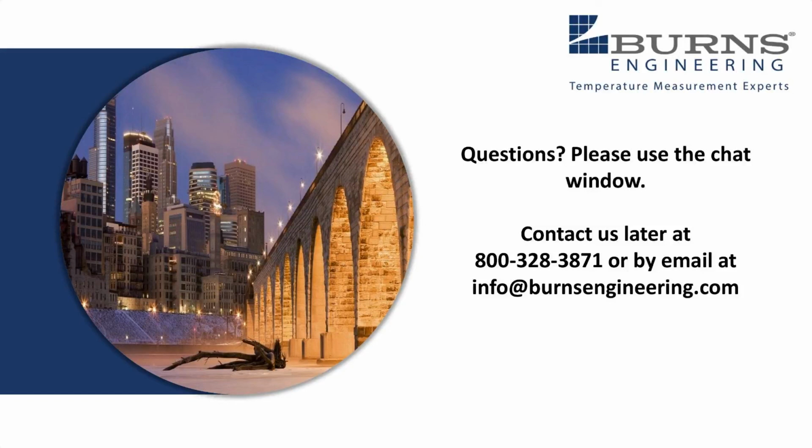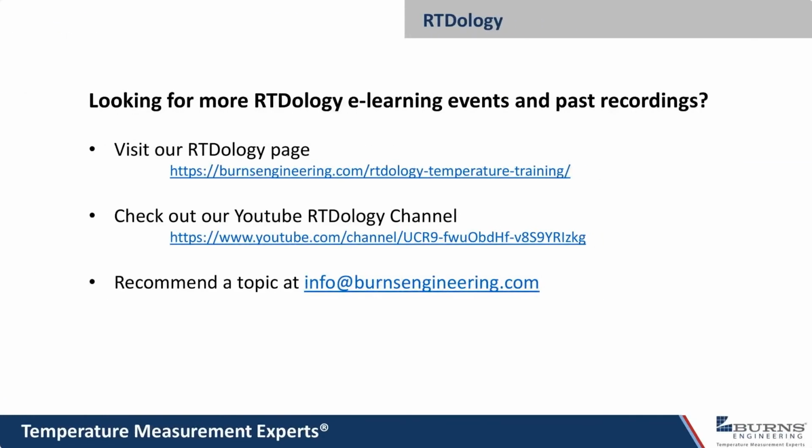And just one more thing to add to that is sometimes there's a misconception that the fastest time constant is somehow a better sensor, or it gives you a better measurement because it's quote unquote faster. In reality, the sensor only needs to respond as fast as the process is changing. So if it takes the process 30 minutes to stabilize, the fact that you have a sensor that responds in 3 seconds, 5 seconds, or even a minute doesn't really matter.